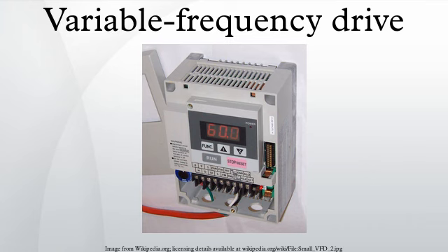Different MV drive topologies are configured in accordance with the voltage-current combination ratings used in different drive controllers' switching devices, such that any given voltage rating is greater than or equal to one of the following standard nominal motor voltage ratings, generally either 2.3/4.16 kV or 3.3/6.6 kV, with one thyristor manufacturer rated for up to 12 kV switching.